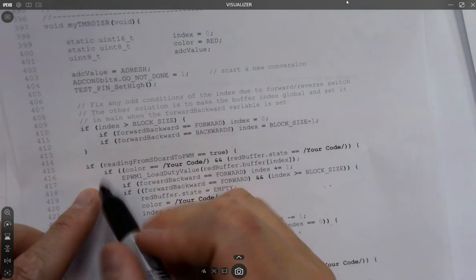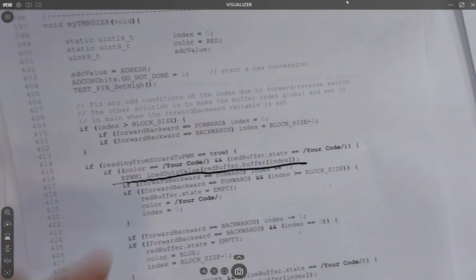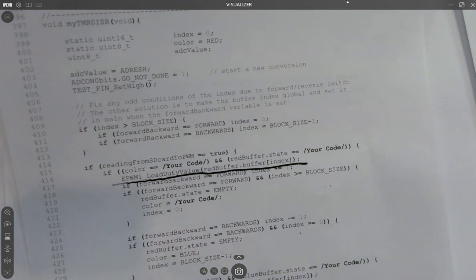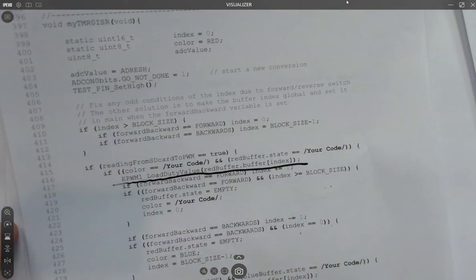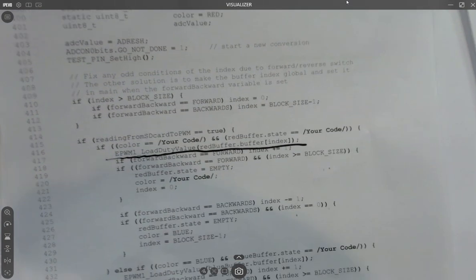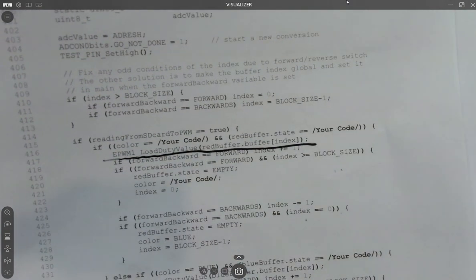So this is the code that does the job, right? Play the song. Could you read it from the back? Remember in the beginning of the class we talked about that, right? How do you play a sound? You need to generate an analog voltage. How is the analog voltage being generated? Low pass filter. The low pass filter is from one pin called RC2, which is the output of the PWM. So that's generating a certain duty cycle and being filtered to generate that analog voltage.